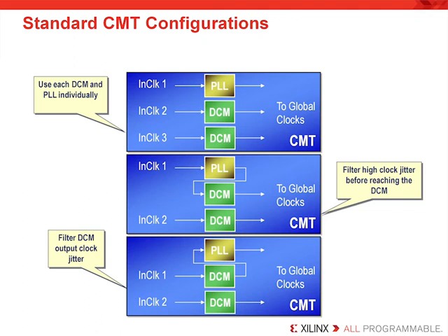In the past, these functions may have been required to be done using external PLLs on the PCB board. Now, these functions can be pulled, and really should be pulled, inside the FPGA since you're already paying for a number of dedicated PLLs. This will save you PC board space and cost, of course. Also note that either DCM in the CMT can be cascaded with the PLL, so there's routing flexibility there.